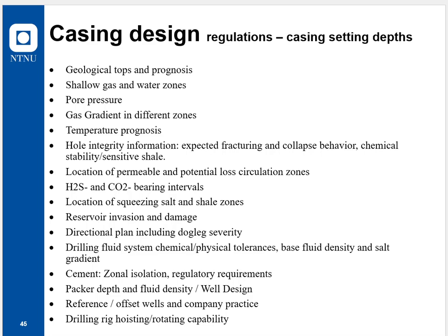Reservoir invasion and damage, directional plan, including dogleg severity. Very often high doglegs would typically add casing wear, or could at least add casing wear of significance. Drilling fluid systems, the chemicals that we are using could in some cases influence our material selection.